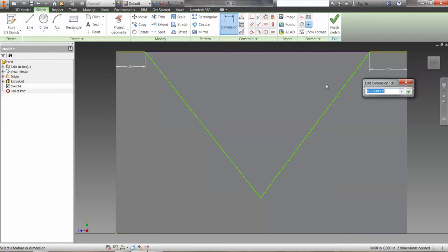And one thing we're going to do for a change here to get this dimension, since it's the same as this, is I'm going to click on this dimension, and that's going to put what's called a parametric modeling here. And this D4 means this dimension, which is D4, dimension number 4, and this dimension, dimension number 5 over here, are going to be the same amount. And so you can see it's fx like f of x. It's a calculation, it's an equation that calculates this dimension based on that one. It's a handy little thing that we may use more later on.